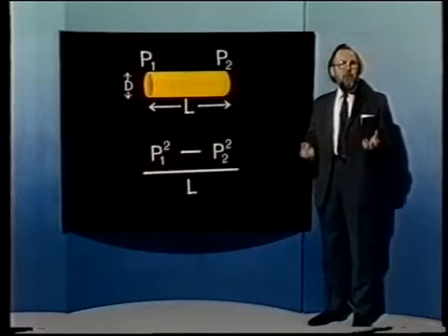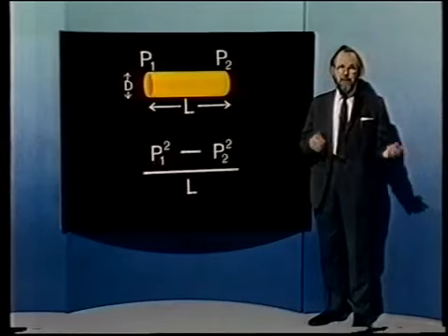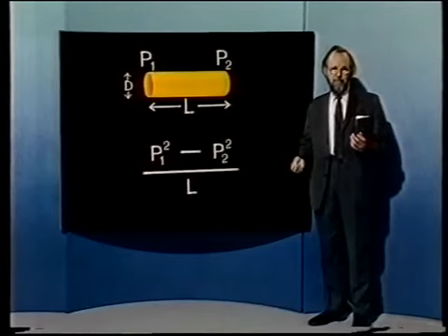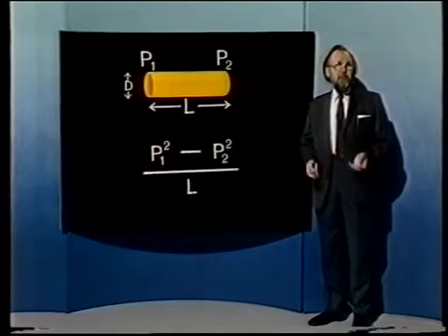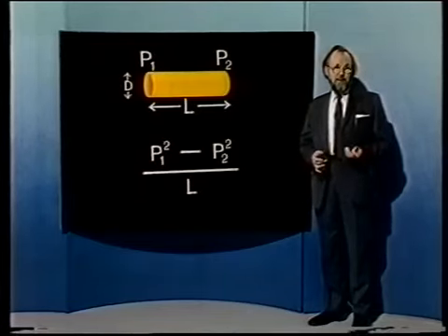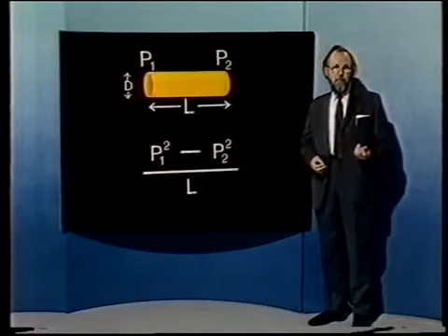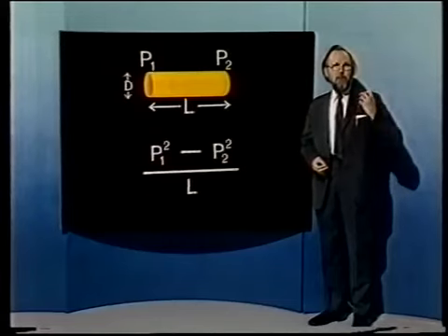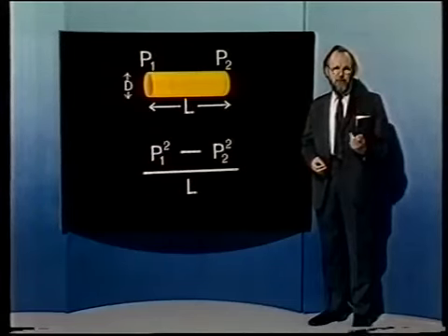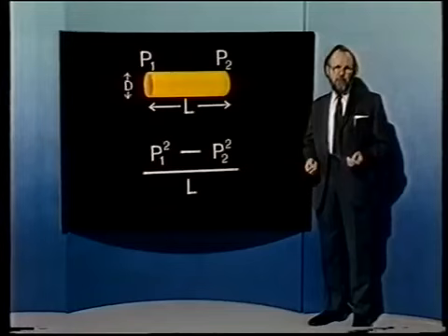So how can we decide which diameter of pipe to use? We have to balance the cost of the pipe against the cost of compression. Well now, pipe is available from the manufacturers in only a limited number of sizes. Let's suppose that there are, say, 7 diameters to choose from. The real problem for Dr. Frank and his team is to reduce the number of choices to manageable proportions. You see, in theory, you could evaluate every combination, but in practice this will be quite impossible.